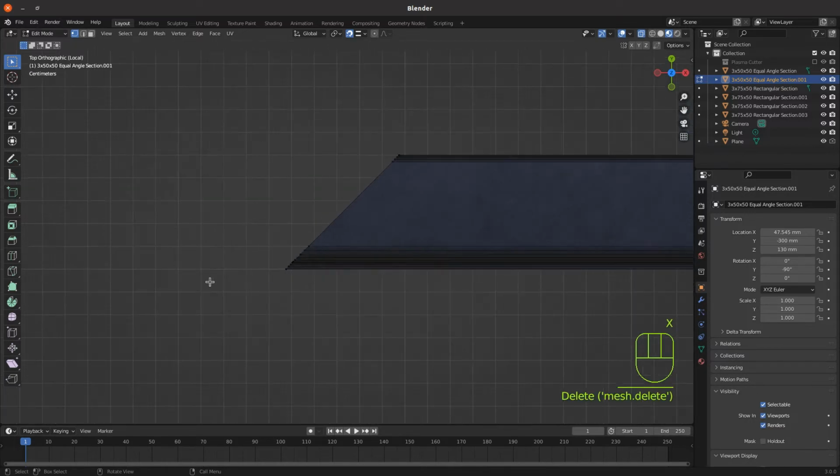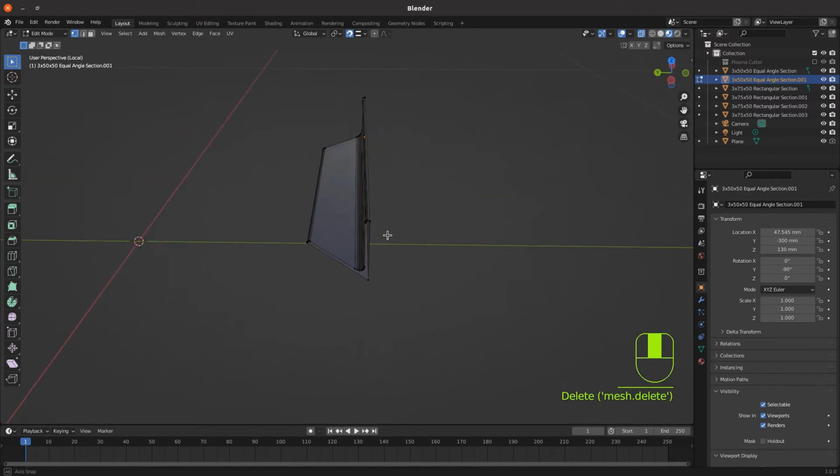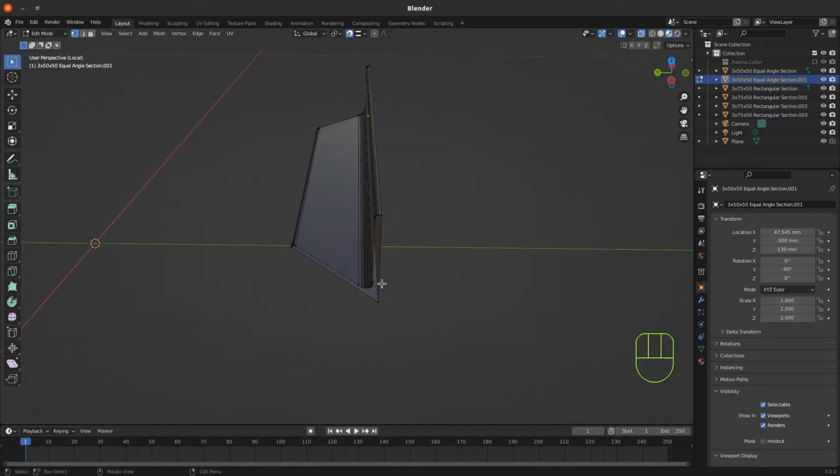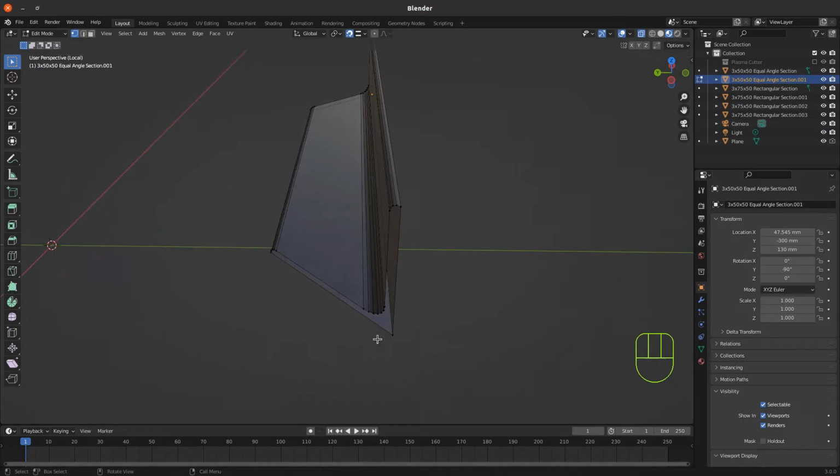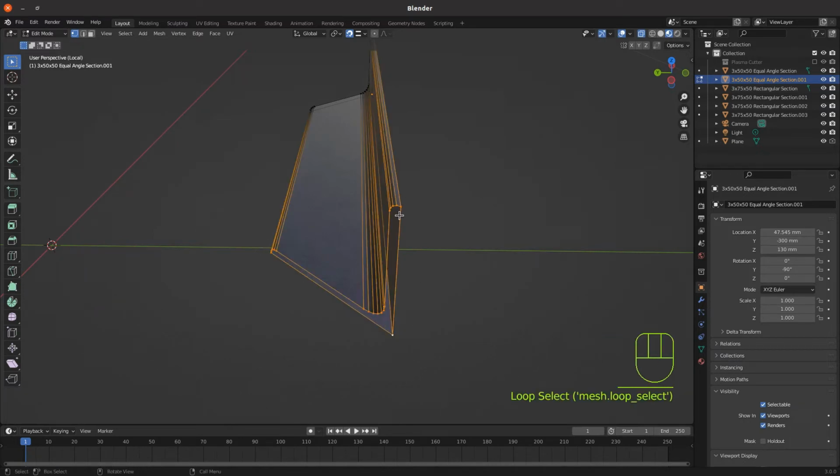And again, we've now opened that end up at a 45 degree angle to the back face of the angle iron. So all we need to do is press the Alt key and left mouse button select one of the open edges that run around the outside, and to fill that press F for face and the edge will be filled. You can take X-ray off so it doesn't show the underlying edges.